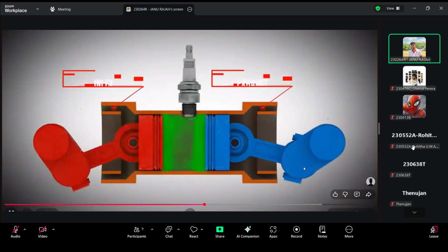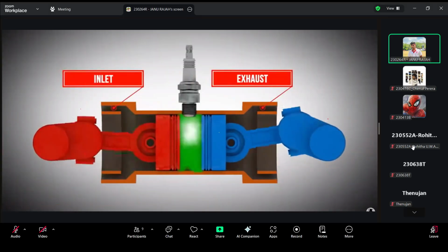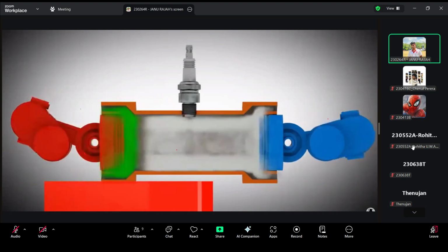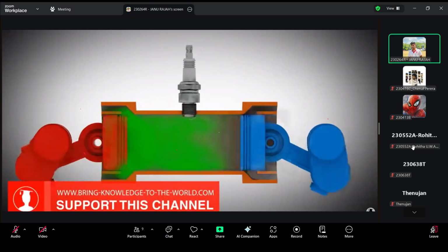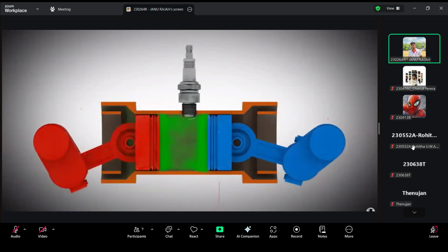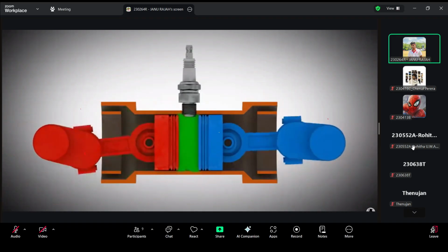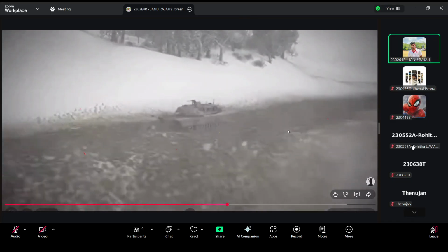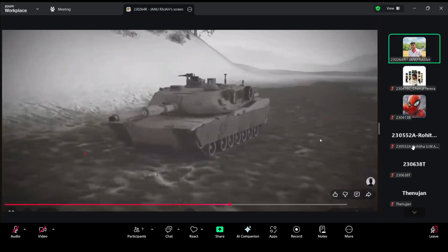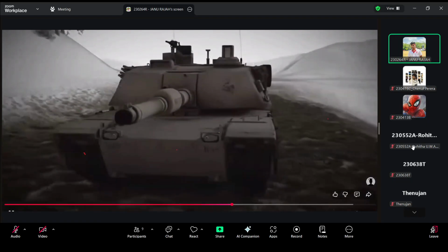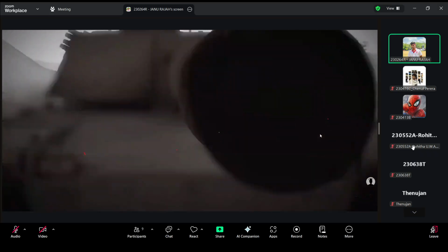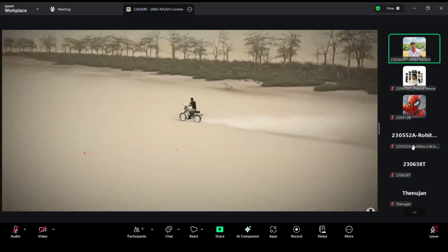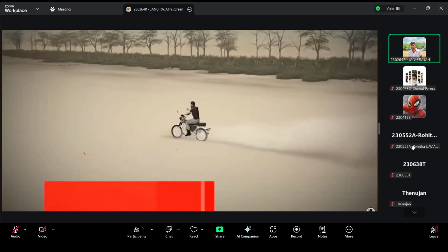Neutral scavenging is another type of scavenging used. For example, in opposed-piston engines, two pistons operate in only one cylinder. Here, one piston controls the fresh mixture flow, whereas the other controls the emission of exhaust fumes. This system is expensive and was used in tanks, but also frequently for large marine diesel engines. Modern engines use loop scavenging, which is used, for example, in the famous Simson mopeds. It is still used in many engines today.